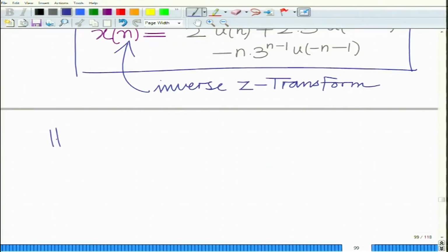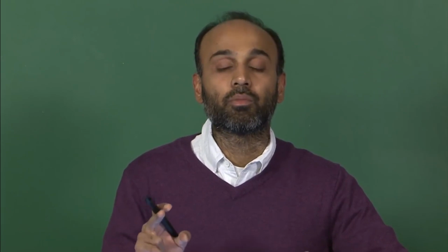Okay. So, we have constructed the inverse z transform of this rational function. Remember, we started with a rational function of z which has a pole of multiplicity greater than 1, a pole of multiplicity 2 at z equal to 3, and that is basically the inverse z transform, which we derived by first constructing the partial fraction expansion and then constructing the inverse z transform of each of the terms in the partial fraction expansion. Okay. Let us look at another example.